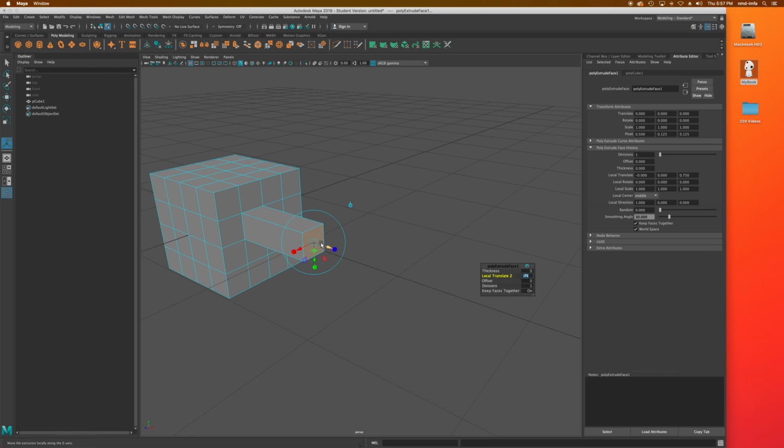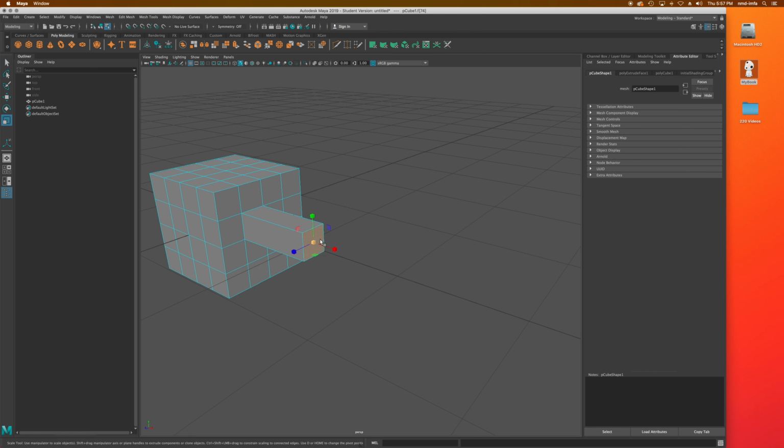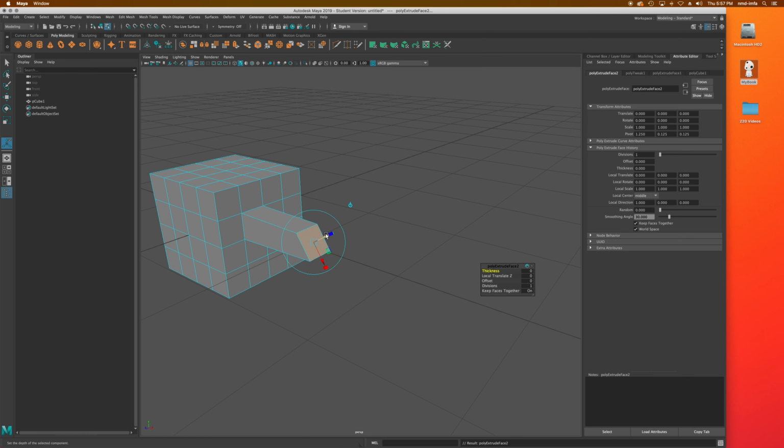Now I still have this selected, and this is where things get really fun with extruding, is you can just continue the extrusions. But I don't have to continue on the same path, I've got this extrusion right now, so I can always take that, click off of it. To click out of the extrusion tool, I just click back onto my main selection tool. I can always rotate this particular selection a little bit, and then Command E again, and continue it.